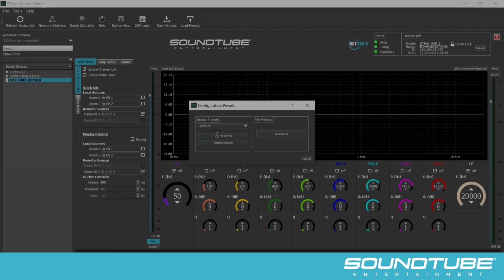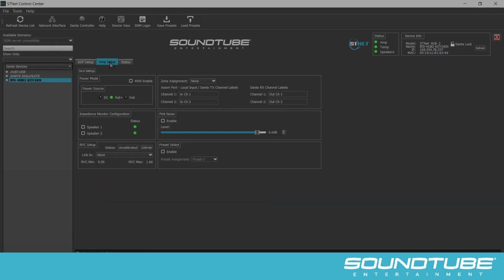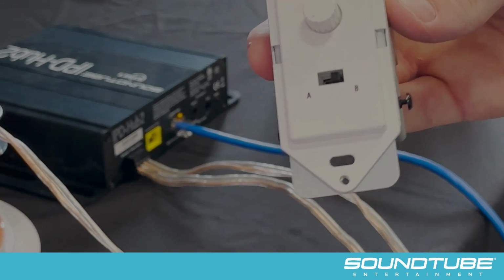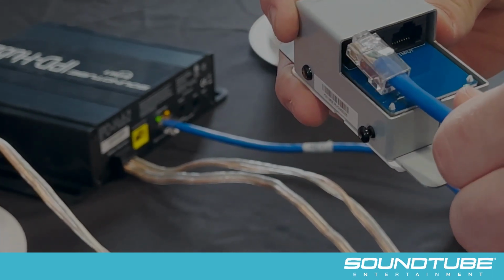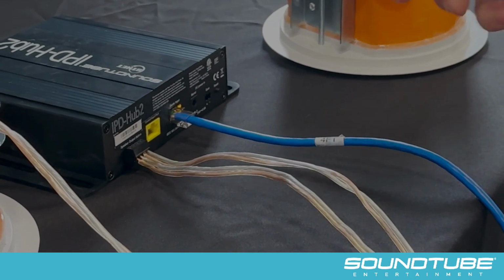We save this as our default preset, which will be our power on default in the event of a power loss or system reboot. Now in the Amp Setup tab, we'll calibrate our remote volume control. Upon clicking Calibrate, the software ensures that you have the RVC installed. The SoundTube RVC1 connects directly to the IPD-Hub 2's yellow input or control port using a standard network cable. It's marked with an output on the back of the RVC.